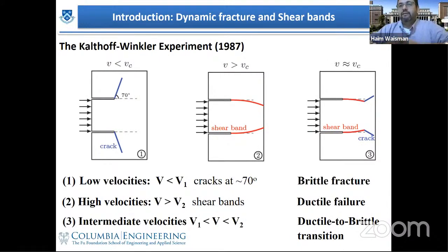I didn't show it here, but if you go back to the tension problem, you will have a shear band, and then this model will create a crack exactly on top of the shear band. And this makes sense because shear bands are essentially a precursor to fracture at the end of the day. The way I think of this is that the shear band is creating a new notch, basically, and this is where the crack is going to start from. It's like a new stress concentration.